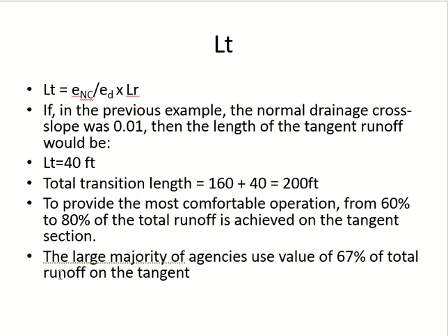But if you do the full change before the curve, it could become confusing for the driver because it will start to change very far from the curve. You are changing the cross section, right? The change of cross section is required at the curve, so the driver is expecting the change on the curve or near the curve. If you do the full change before the curve, that will happen very early. It may confuse the driver.